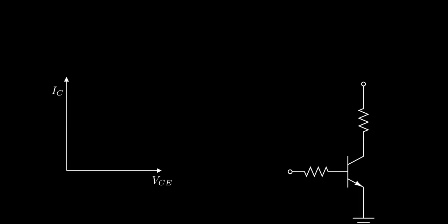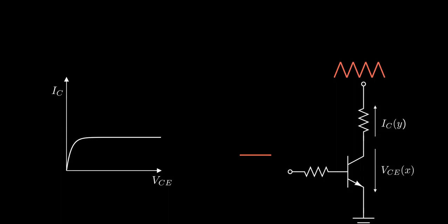Before starting right away, we need to understand how a curve tracer works. The idea is quite simple. We just need to sweep the collector voltage with either a triangular or sine wave and measure the collector current. These will be respectively the x-axis and the y-axis.